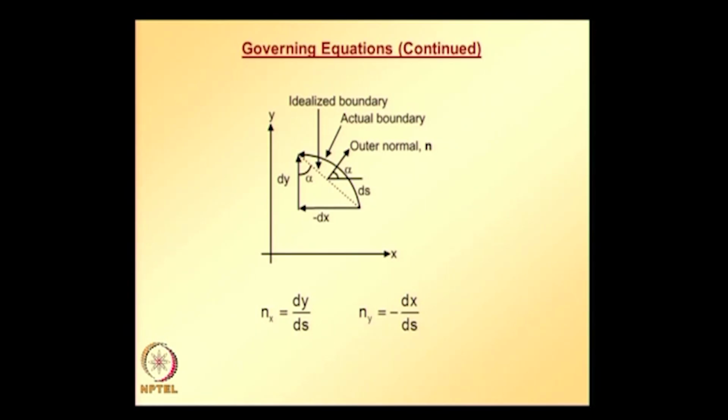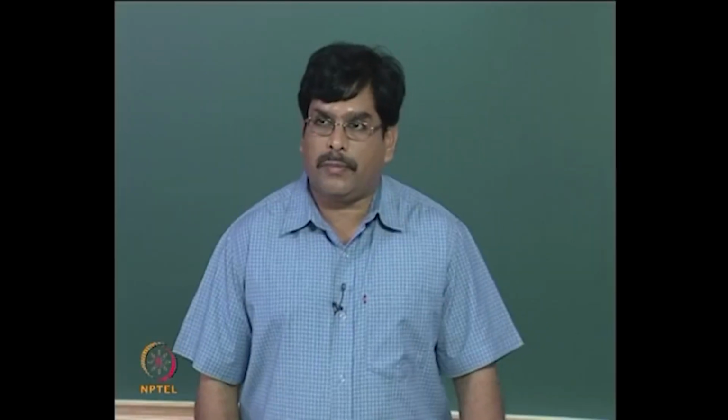And the surface forces can be expressed in terms of the primary unknowns, the displacements, by first writing the tractions in terms of stress components, and we know how to express stress components in terms of displacement components.